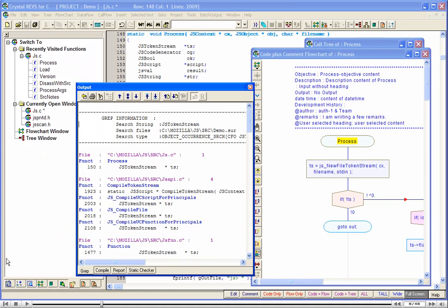When you drag a floating window, it tries to dock whenever it touches the boundary of an area. If you do not wish to dock it, just keep dragging it further. If you wish to prevent the window from docking, press the Control key while you drag the window. Let us dock the Output window below the Browse window. We will click on the title bar until it docks.